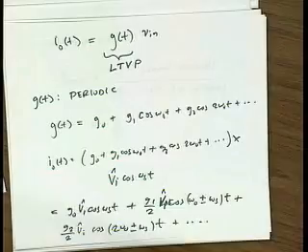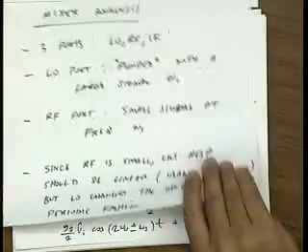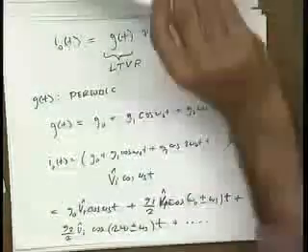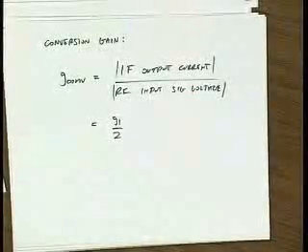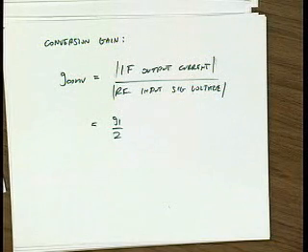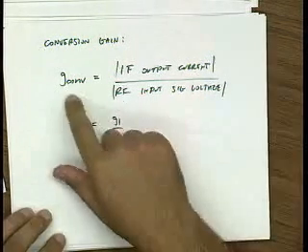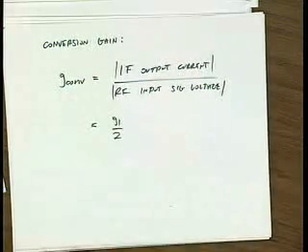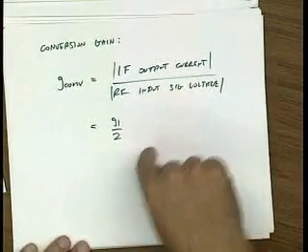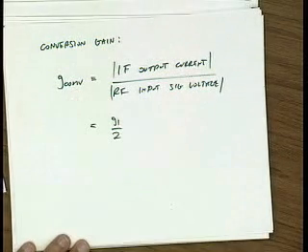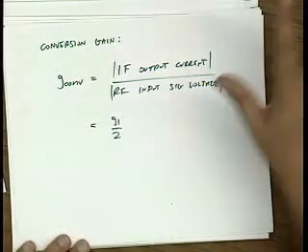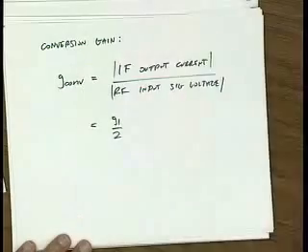Could you go back to the final slide with the conversion gain? That's G1 over 2? Yep. G1 is the first harmonic of the periodic LO. So G conversion looks like a transconductance between the input and the output. The difference, though, is that the input and output are at different frequencies. That's why we call it a conversion gain. So signal comes in at frequency omega s. The output current is at frequency omega s minus omega naught.